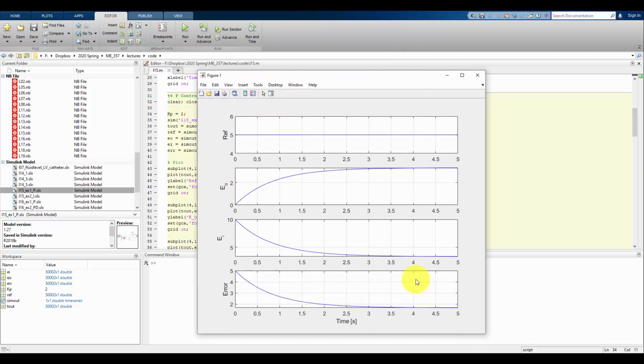Right, simulating this, we see that as K increases, for this plant at least, the final value of our output voltage, E out, should be 3.33, 3 1/3. It should asymptotically approach, so we're closer to that 5 volts. We're clearly not there yet.